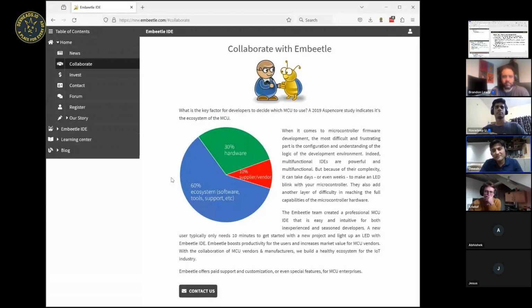So I choose devices in a way that my resources and my in-house skills are trained for. And another aspect is how big the user community is and how openly people are talking about its features. Because if there are features but not enough supporting documents, then it's a risk putting 6 months into implementing the features, and then even with the power consumption, you reach the same point which your other MCU is giving. So you end up wasting a lot of your time, and maybe sometimes skills also matter. So I think I choose it that way. Great.